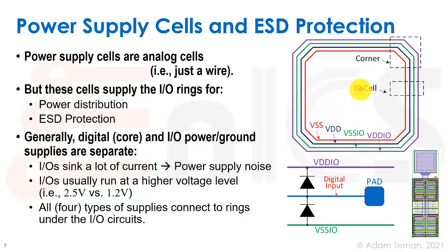But since we need to provide the 4 power supply IOs for that area, we need to have a sufficient number of IOs in order to really utilize the fact that we would have our IOs sitting in the middle of the chip. So even in flip chips, we usually do put all the IOs around the periphery and only have power connections come into the middle of the chip. Maybe we can have some secondary type of IO areas, but it's not usually the case. Usually, even on the flip chips, we have this IO ring around.